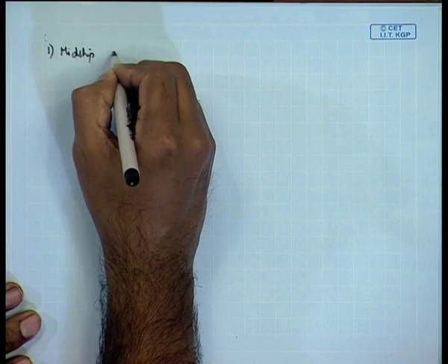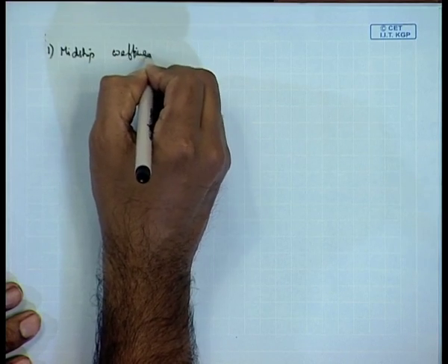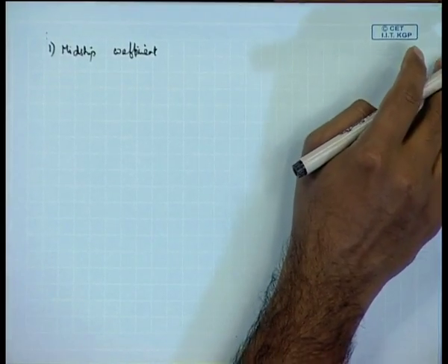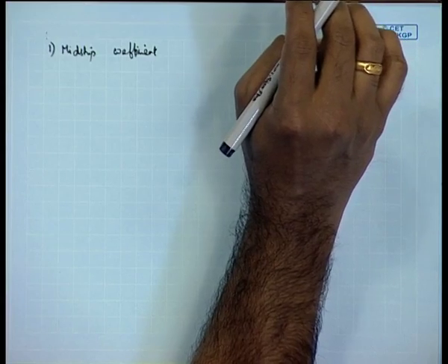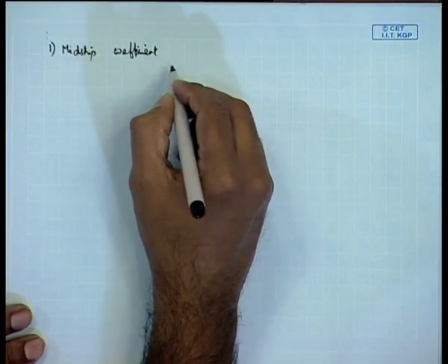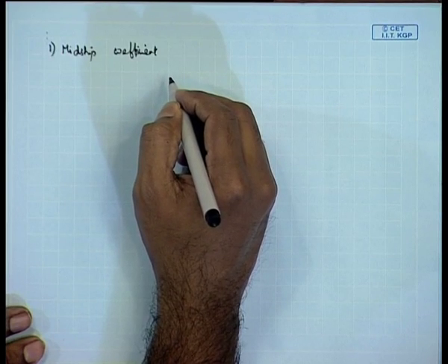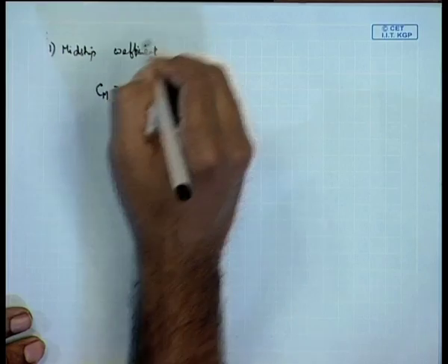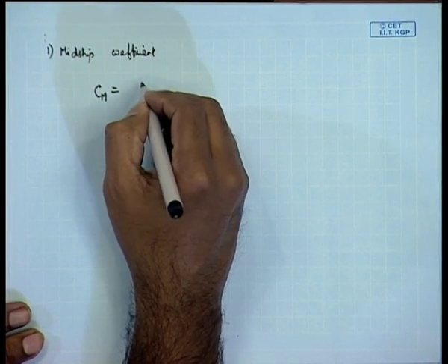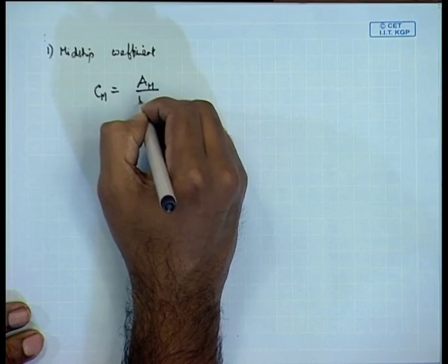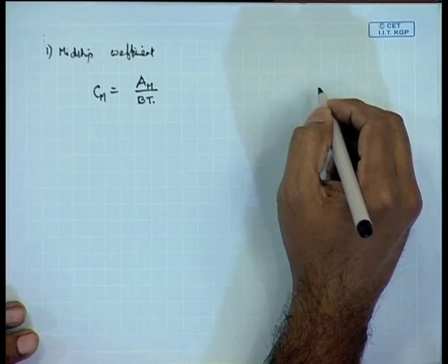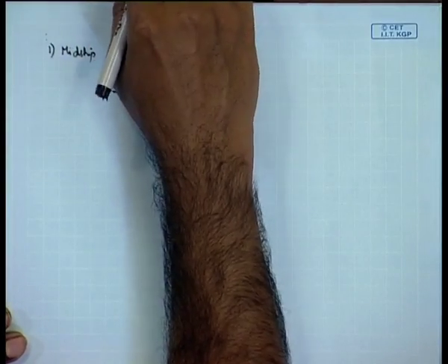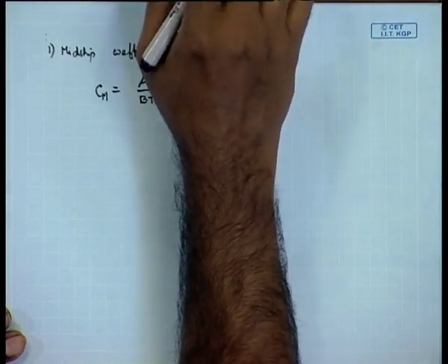One of them is the Midship coefficient. It is known as the Midship coefficient. It is defined as the ratio of the sectional area underwater to the breadth and draft, which means it is defined to be Cm. Cm is equal to Am by B into T, where Am, as I told you before, we divide the ship in two ways.